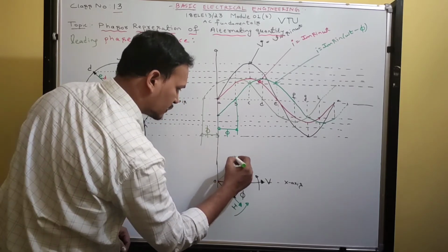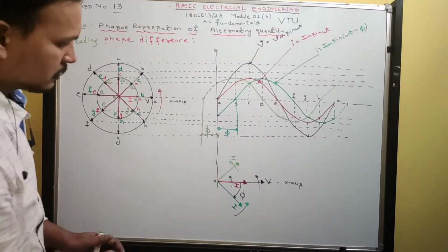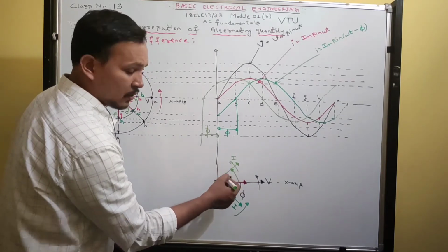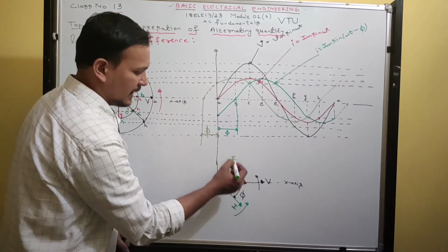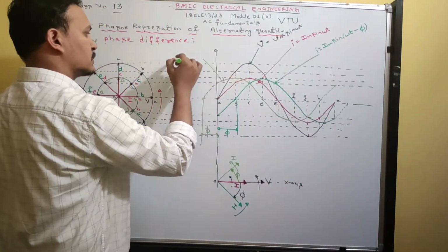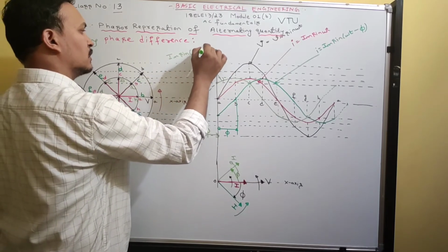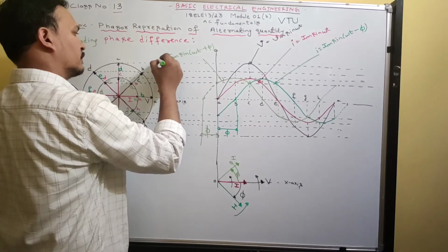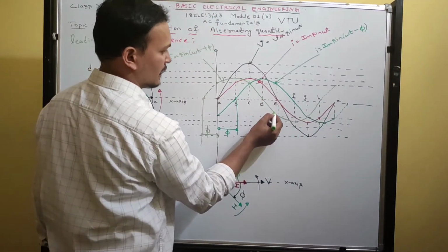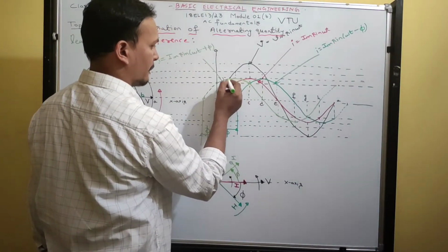Okay, now this is current. I need to rotate this phasor in anti-clockwise direction. How to measure the angle? Angle is measured in anti-clockwise direction for positive phase. Means what? Leading. So, how to write this green color waveform? What is this? Im sin omega t, you should write plus pi. So, the instantaneous equation for this waveform is Im sin omega t plus pi.